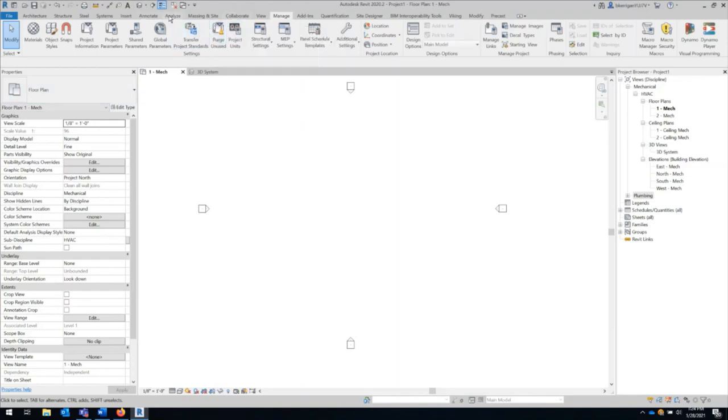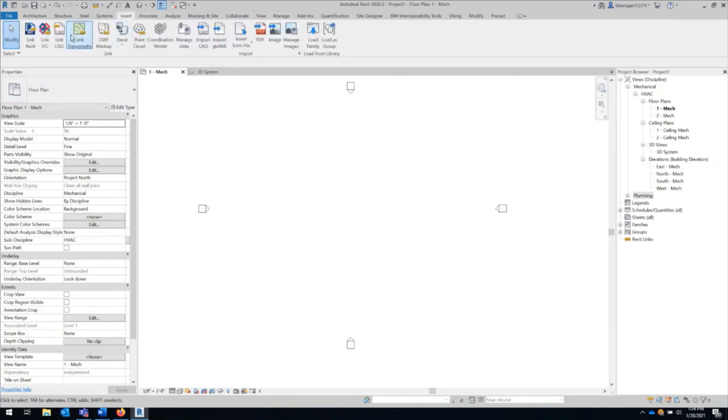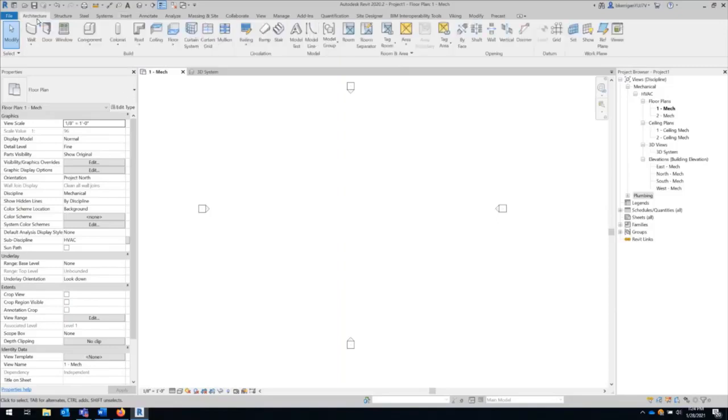So generally when you start, you may have something like an existing Revit model. In that case, you could go to the Insert tab and link to that existing Revit model. You may have had a CAD model provided to you. You may even just be working on some type of PDF. Usually you can import those, use them either as the reference geometry or simply trace over them to create some sort of reference geometry. But just for the sake of simplicity, we're going to draw a couple walls here and start from nothing.